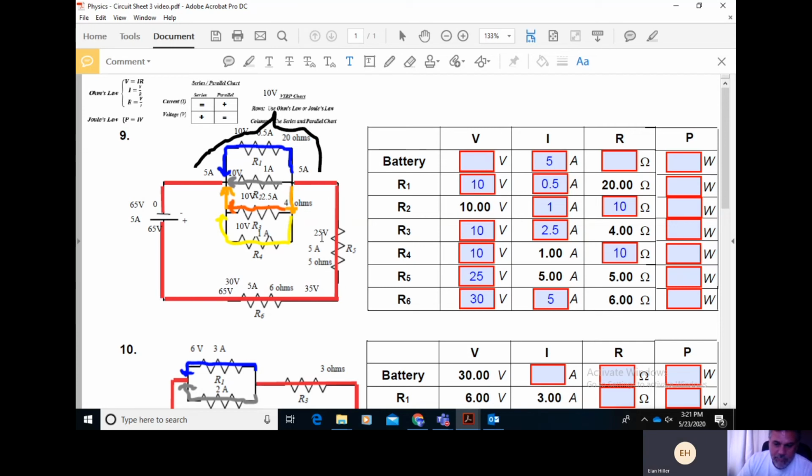Crossing this resistor, we drop 25 volts of potential from 35, so now we would be down to 10 volts of potential. Going into the last bit of resistance, we are dropping 10 volts of potential, which brings us down to 0 volts. The sum total of the voltages has to add up to 0, meaning you subtract the voltages as you go all the way around until you get to 0. So it checks out.